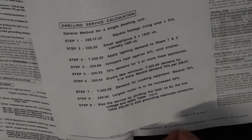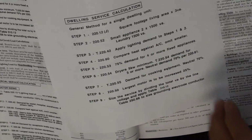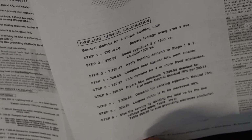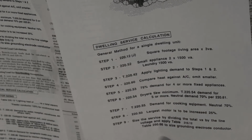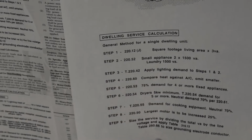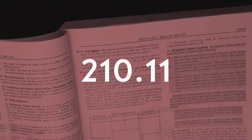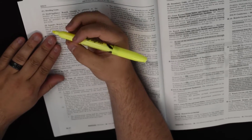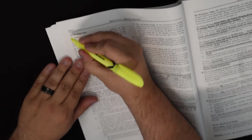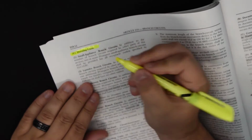We're going to go through the book and highlight certain pieces that you have to know in order to use this 9-step format. Certain things you have to know before you can do a load calculation, a dwelling unit service calculation. It's in the code book and it's hidden. So we're going to turn to Chapter 2, Article 210, Part 11. We're going to go to the dwelling unit specific, which is C. And we're going to take our light color highlighter and highlight the dwelling unit specific part, 210.11C.